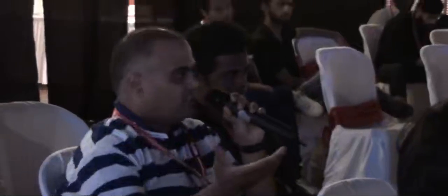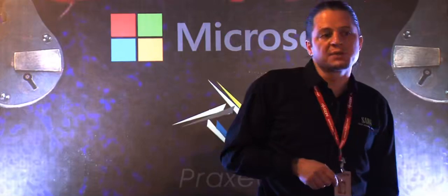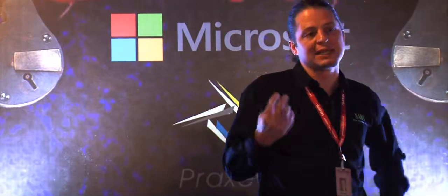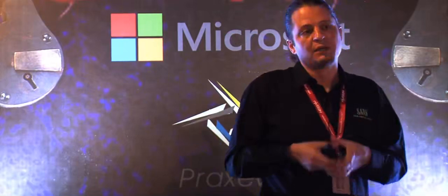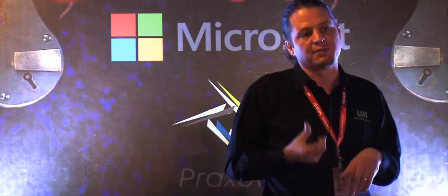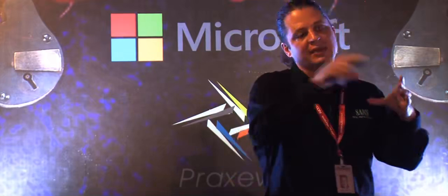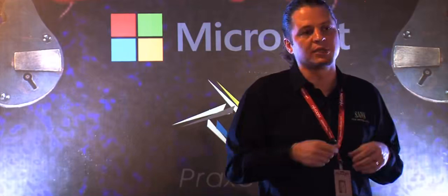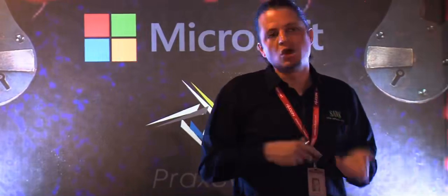Yeah, because as he said, simulation, yes, we can't cover everything. But most of the products, at one point or the other, are using the SOCs these days. Yeah. So for those SOC testing, are there any tools in your framework? I don't currently have any tools in the framework to work directly with system on a chip, because usually when you're working at that level and you're trying to attack the components of a single chip, then you're going to have to be decapping it, taking it under an electron microscope, taking imaging of it, and then using some type of software or decoder to try to take that image back to the actual binary bits saved on that system on a chip. So tools like that, no, I do not have.